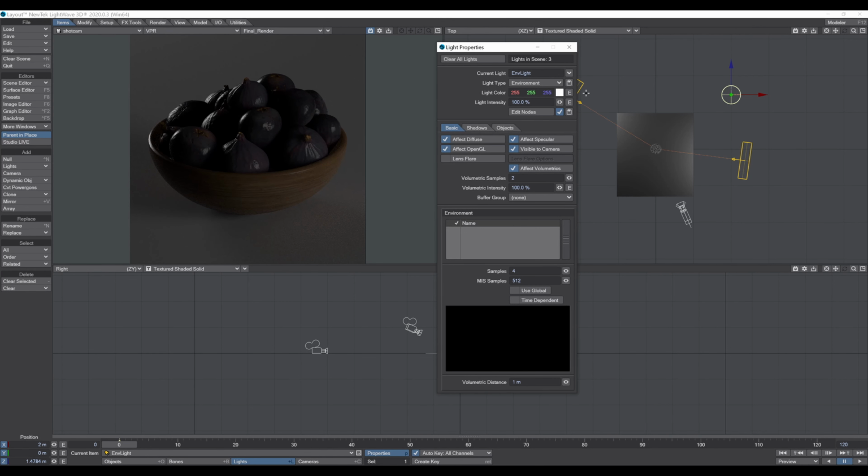And these two lights here and here just support the focus, bringing up the reflections or the rim lights and stuff like that. But for the overall light situation, I would use an HDRI image. So don't be scared to use HDRI images combined with other lights. Okay, so it's totally okay to light up a scene like that.